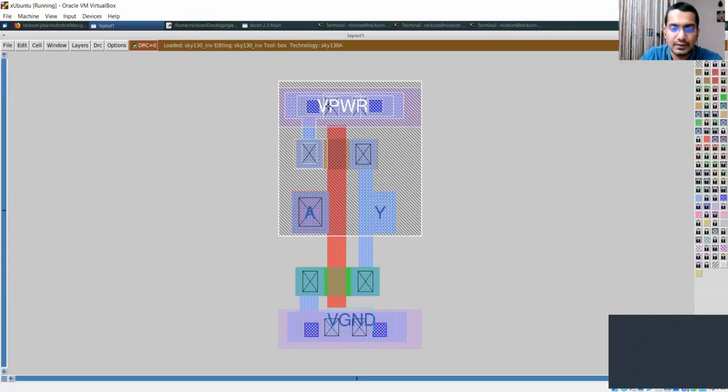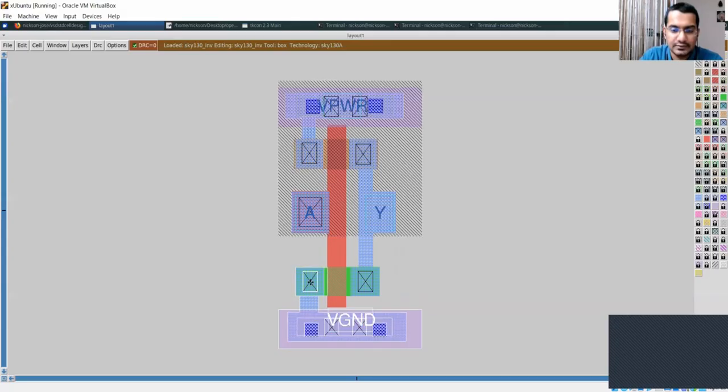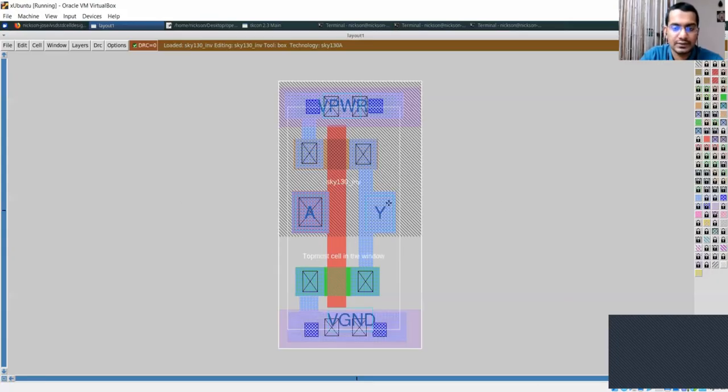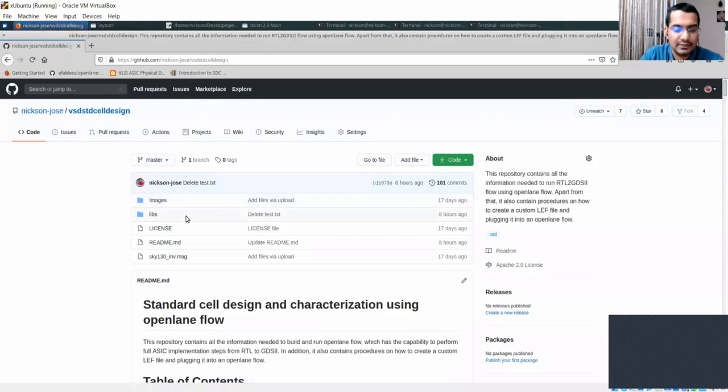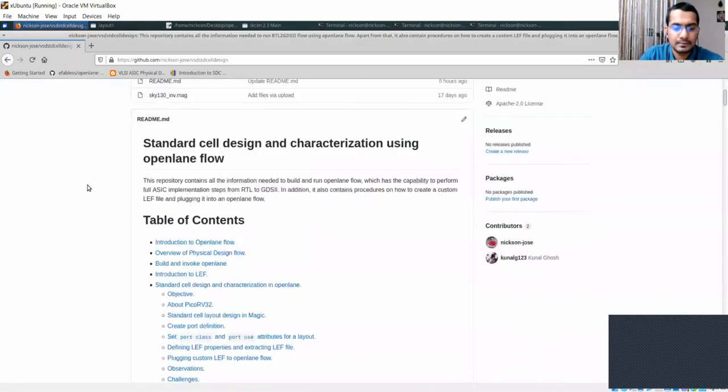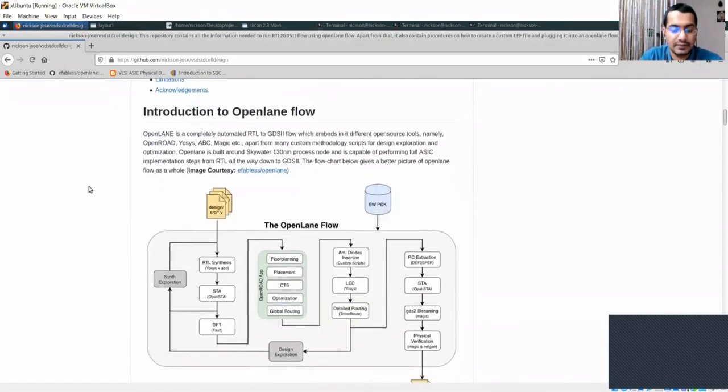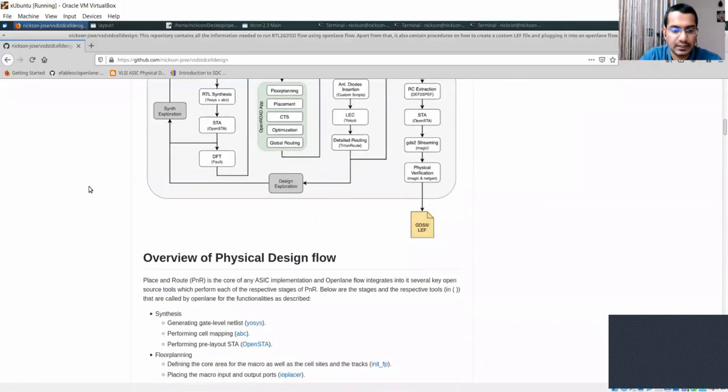So now you have this aluminum in contact with the bottom layer over here. You have this aluminum which is in contact with this particular layer. You have this aluminum which is in contact with this layer. So the contacts are produced, and the interconnect sizes are increasing as we go to the higher metal level layers. So the next step is to remove the resist, and now you have your second level of metal. So you have your local interconnect, the zero level of metal, and your first level of metal, which is the aluminum interconnects.